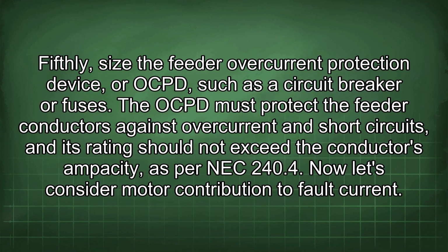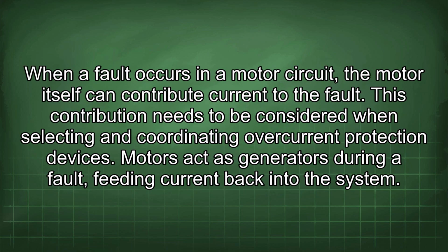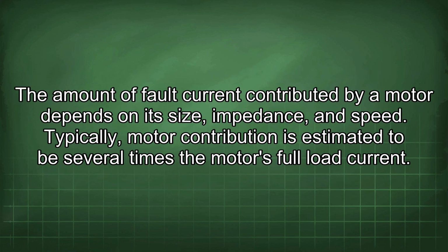Now let's consider motor contribution to fault current. When a fault occurs in a motor circuit, the motor itself can contribute current to the fault. This contribution needs to be considered when selecting and coordinating overcurrent protection devices. Motors act as generators during a fault, feeding current back into the system. The amount of fault current contributed by a motor depends on its size, impedance, and speed. Typically, motor contribution is estimated to be several times the motor's full load current.